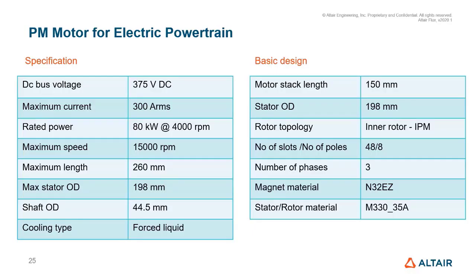Now I will show you how Flux Motor actually works through a demo. In this demo, we'll be designing a PM motor for an electric powertrain to meet the specification on the table on the left here. From this specification, we typically go through analytical calculation to estimate the main dimensions of the motor. In this case, I have a stack length of 150 millimeter and the stator OD of 198 millimeter, and then we have to